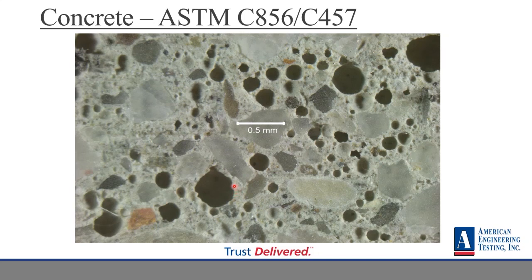They have a chemical admixture that they add to the concrete, and they need a certain percent, and it has to do with the freeze-thaw durability of the concrete. In Minnesota, typically for our pavements, our DOT will specify 5 to 7% air entrainment. This helps the concrete expand and contract almost like a sponge during freeze-thaw cycles. I think they even spec air entrainment down in Georgia and different places, so it's very common to see air entrainment.